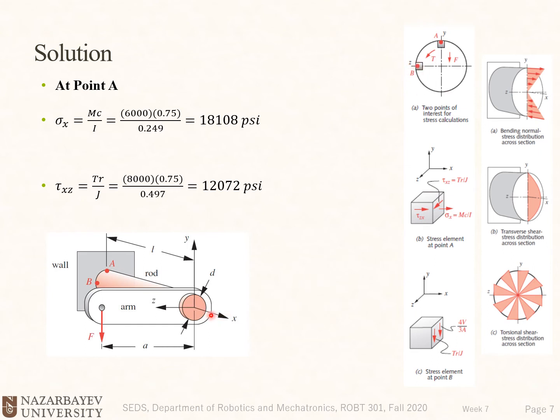Also be careful of the coordinate system, since the x axis is perpendicular to our surface. All these subscripts start with x, and we need to see the second subscript. The second one shows the direction of stress. For the normal stresses, we said that we reduce subscripts to 1, so we only have one, sigma x, and for the tau xz, I will explain it.